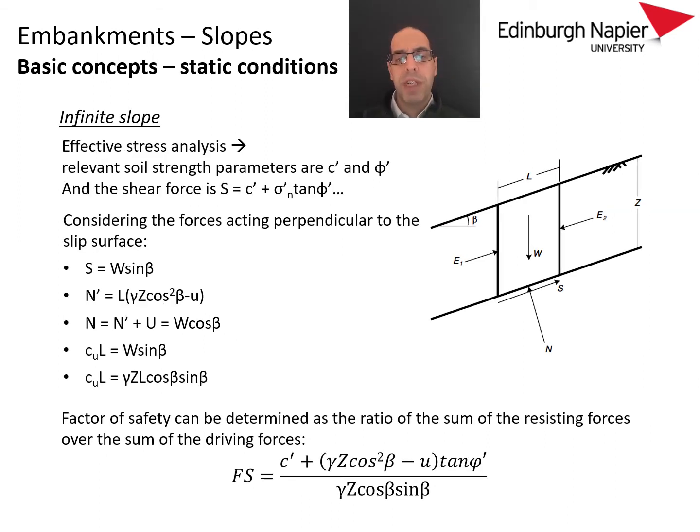Of course, you can extend this to include groundwater levels and seepage forces, and you can find the factor of safety in the same way by doing a static equilibrium along the slip surface. But if you want to see the full details of how that is obtained, as I mentioned before, just let me know and I can show you the full solution by uploading the slides into Moodle.